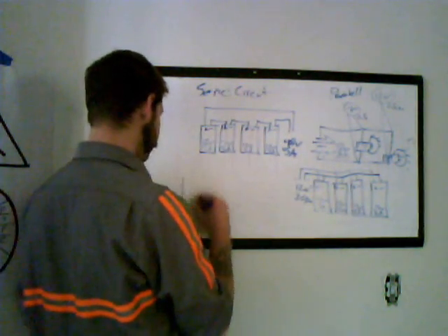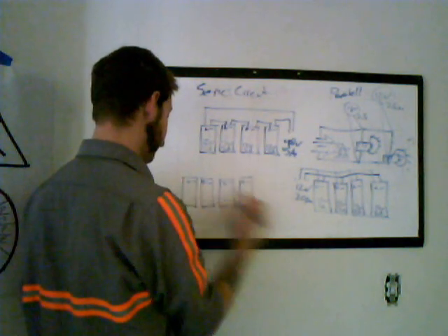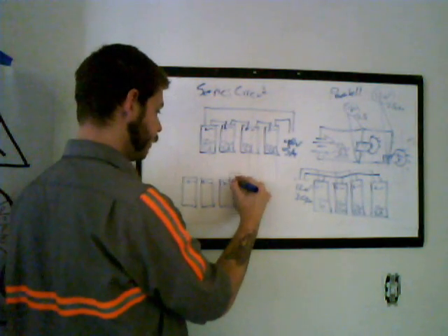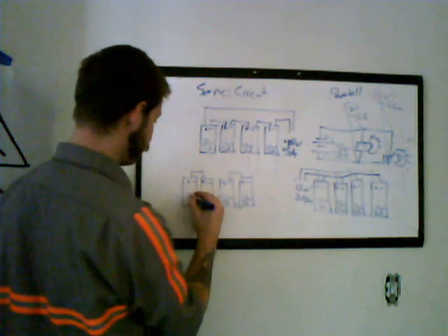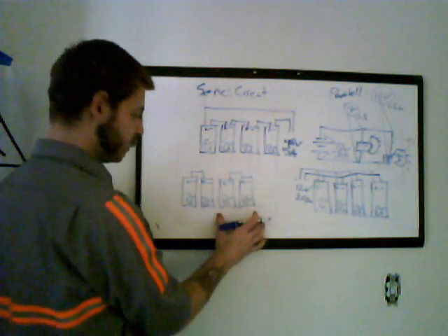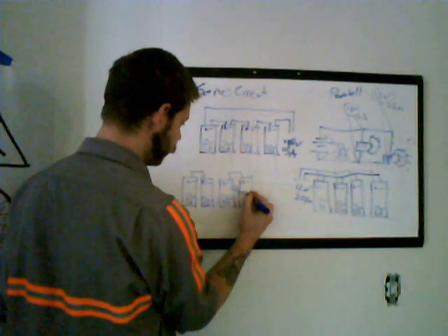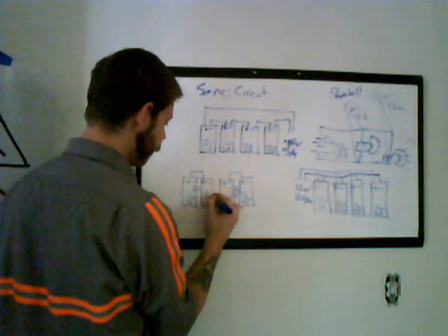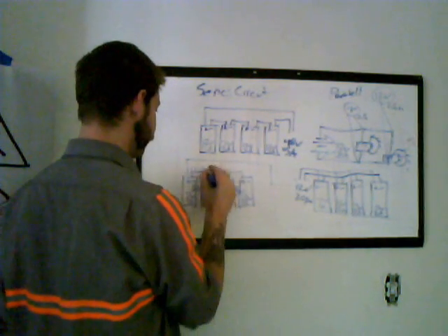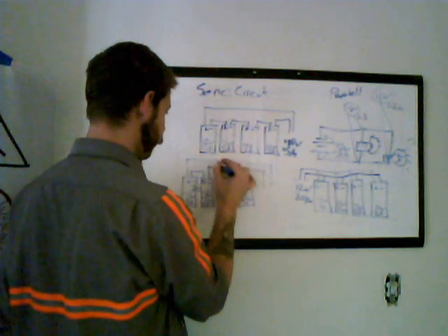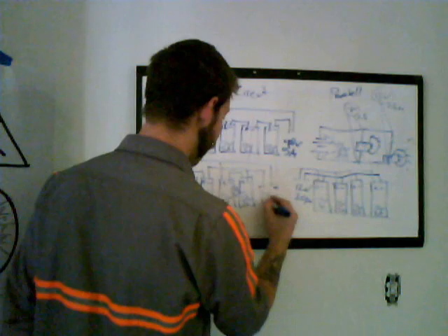Show you one more example. The same 4 cells. Put these two together in series. Put these two together in series. That means this is 12 volt, 5 amp. These two sections, the way they're put together right there, are going to make it 24 volts, 5 amps. This is going to be a 24 volt, 5 amp section 2. You connect those two together in parallel. Bring the positive ones out right there, the negative ones out right here. What you have is 24 volts, 10 amps.